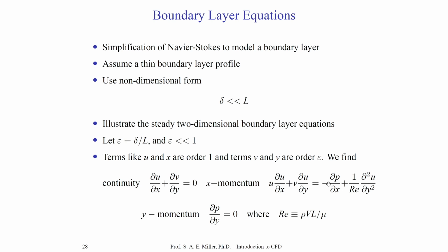You'll see you still have a pressure gradient in the x direction. Many boundary layers are studied with partial p partial x is 0. And then of course you'll just find the left-hand side equal to the right-hand side viscous term. This is the so-called zero pressure gradient boundary layer case, and that's simply setting partial p partial x to 0. The continuity equation remains as incompressible and steady.